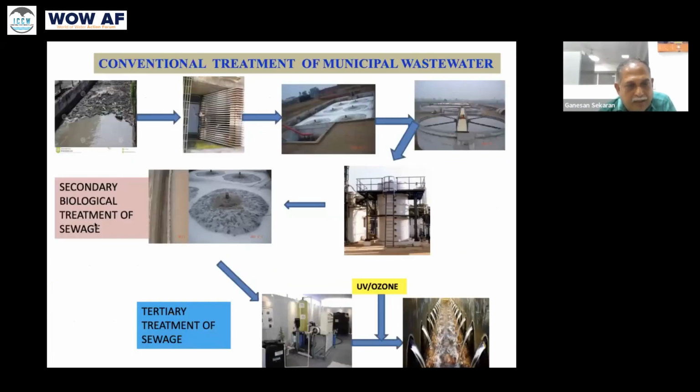The flow goes to a collection tank, then to the screen to remove floating solids, then passes to the equalization tank, and of course the settling tank to remove grit. Certain flow sheets have anaerobic treatment followed by the activated sludge process. All the configurations available so far have the activated sludge process. After this, suspended solids or biomass are separated and the water is recovered, or after disinfection the water is fit for discharge into the sources pointed out. But since zero discharge has been enforced by the Pollution Control Board, they now have to use ultrafiltration to recover water for utility purposes, as already given on the flow sheet. Municipal wastewater discharged from the CSTPs or STPs must involve ultrafiltration for reuse purposes.